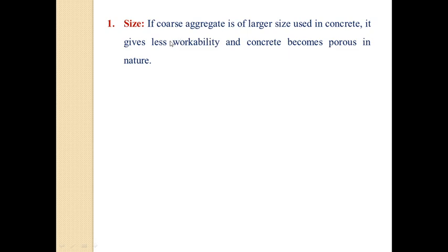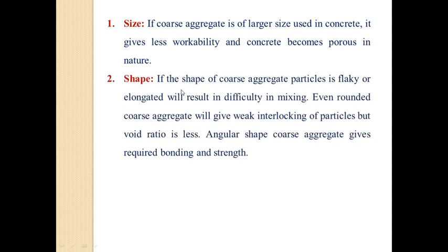So this size factor gives various effects while mixing the concrete. The coarse aggregate should have a medium size, so the concrete does not become harsh and is a good workable one. Next is the shape.